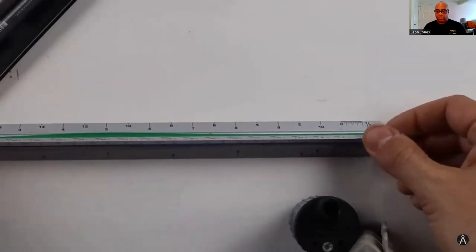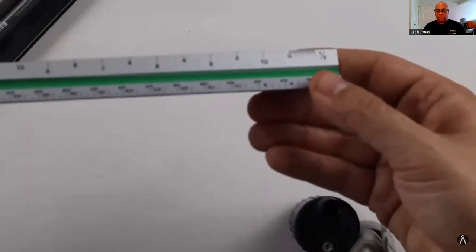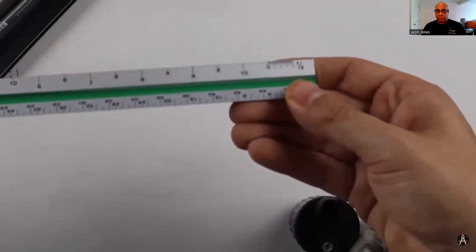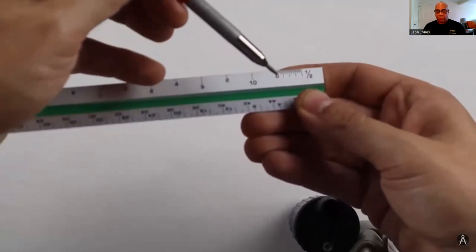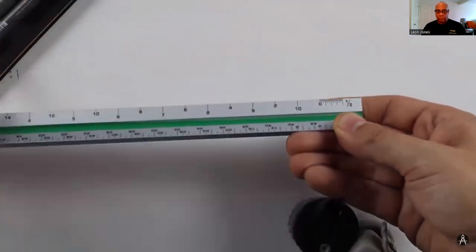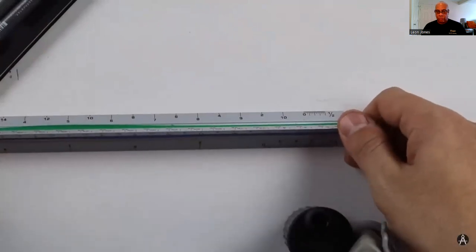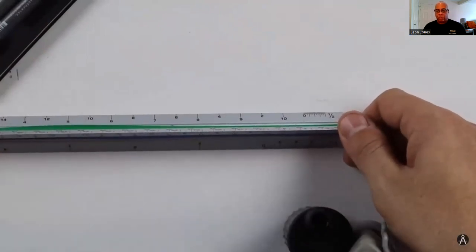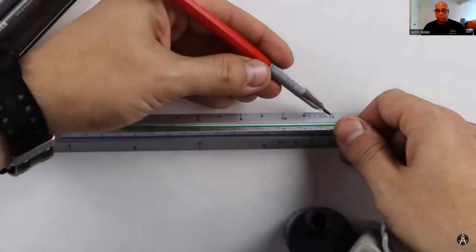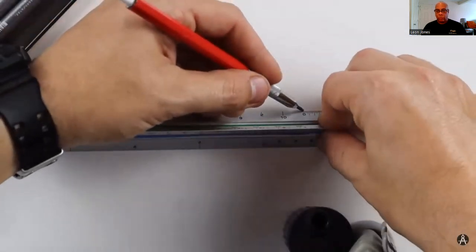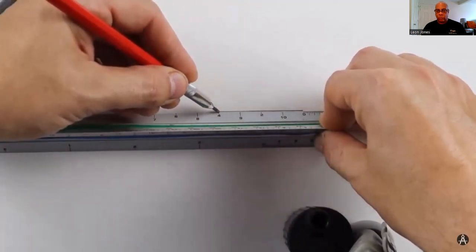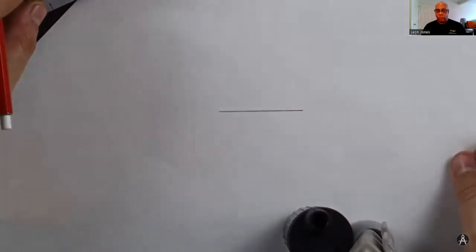So if I'm using my 1/2 inch scale, I'm going to start from that 0 right here, and I'm going to work right to left. So I'll lay it on my drawing. Let's say that I want a line or some sort of edge to be 4 feet long, in half-inch scale. Here's the half-inch, so I'm at the right point. I start at the 0, and then I'll simply hold, and then I'll draw from the 0 to the 4. And that's indicating that that line is 4 feet.